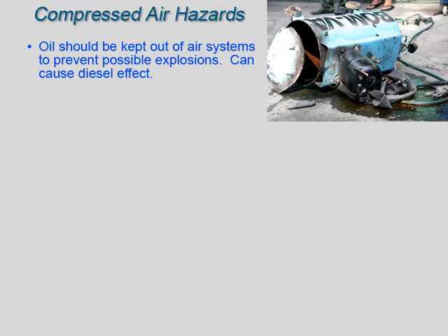Oil introduced in an air compressor can be compressed to the point where detonation occurs, in the same way that detonation occurs in a diesel engine. This detonation can cause equipment damage and personal injury.